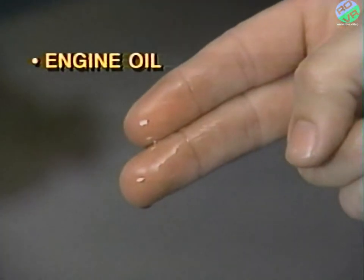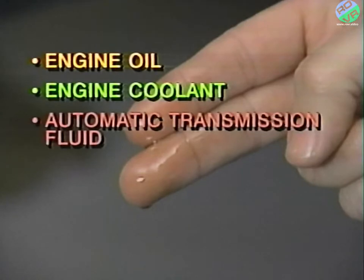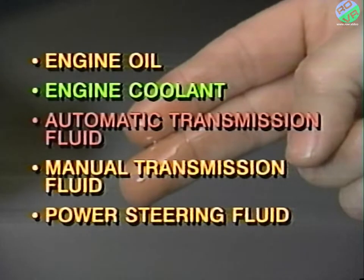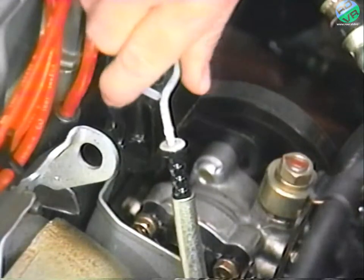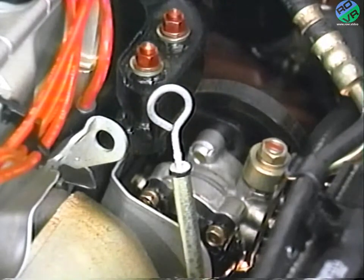Engine oil will be amber or black. Coolant will be green. Automatic transmission fluid will be red. Manual transmission fluid will be amber. Power steering fluid will also be amber. If the leak is engine oil, check for oil being blown out from a loose dipstick.